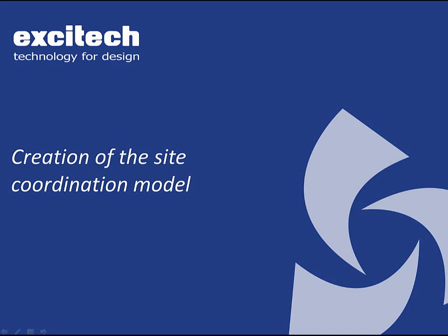Other things to note here is you should never move a model live in the file. In other words, you shouldn't ever go into a file and try and use the move command on a model to move its origin position. The model will literally pull itself to pieces and you will get lots and lots of error messages.